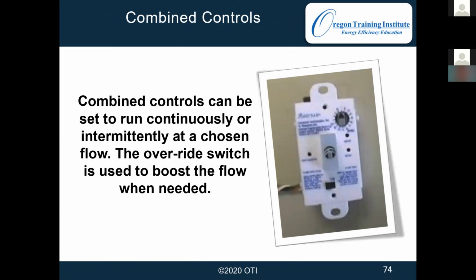Then there's a whole series of smart switches, some of which can be combined with existing fans to make them meet ASHRAE requirements. Though you do want to make sure the fan and the switch are compatible. You know, some fans are DC and some switches are not, and vice versa. So just want to make sure they're matched so that it won't burn the fan out prematurely.